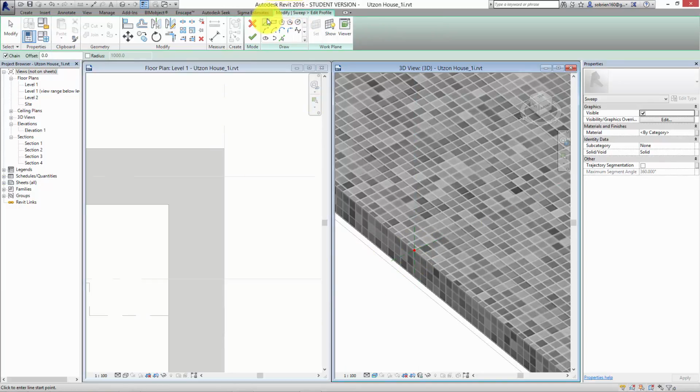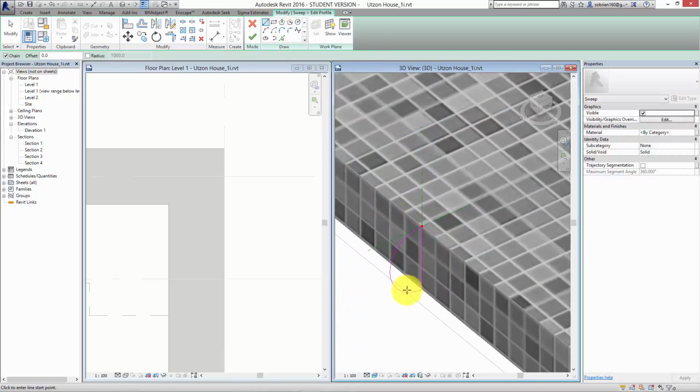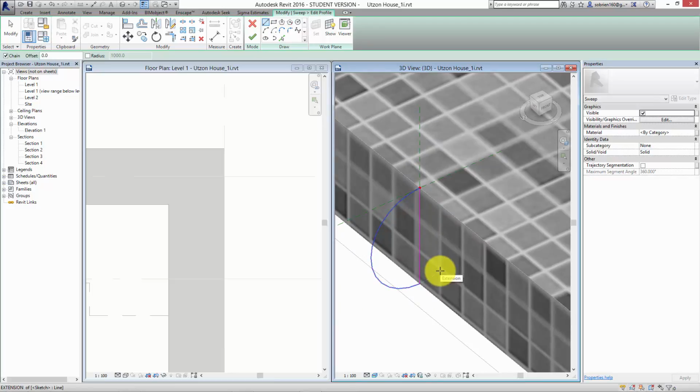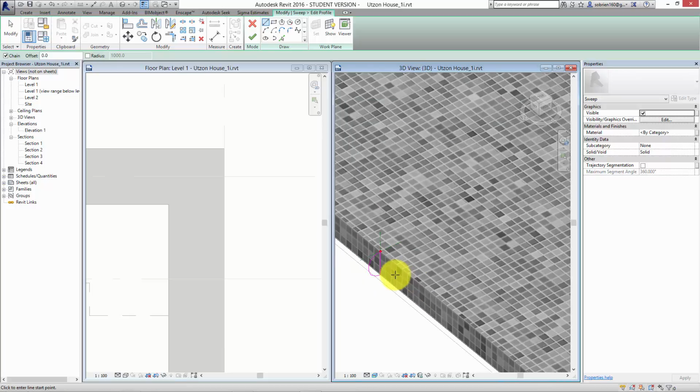So now I'm in here, and you can see we've got the usual drafting tools that Revit has. So I can come in here and let's put a curve in there. So I'll just say put the start here. I'll put the end down here. I'll take a curve out, and then I'll go back and draw a straight line like that. So I've kind of made that half circle shape. So we're going to have a curved edge for this counter is the idea there.